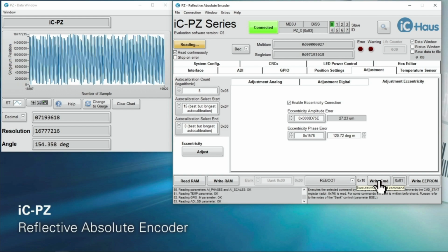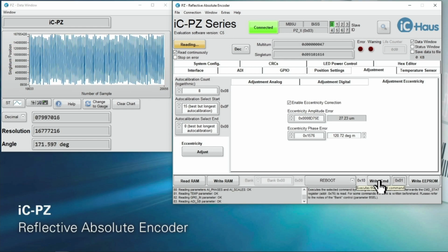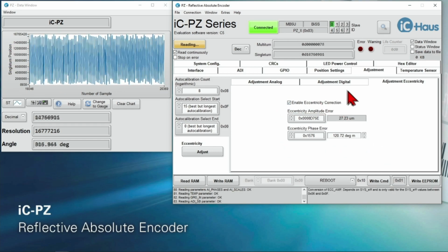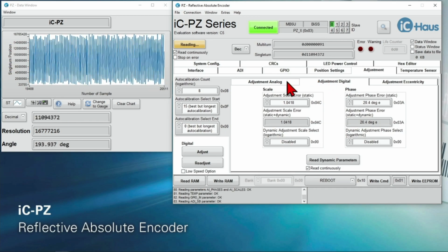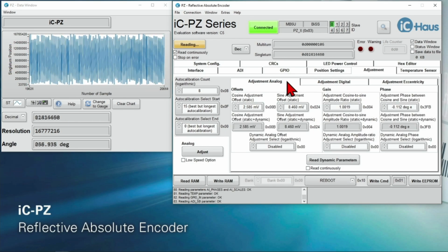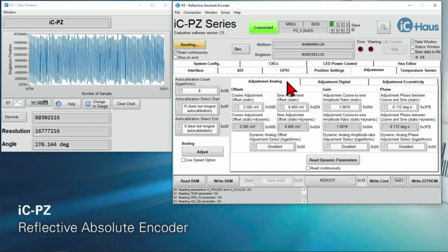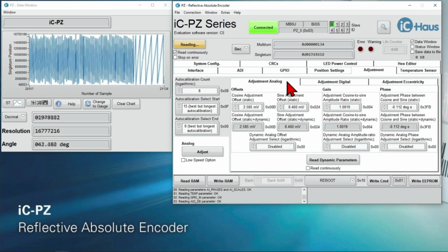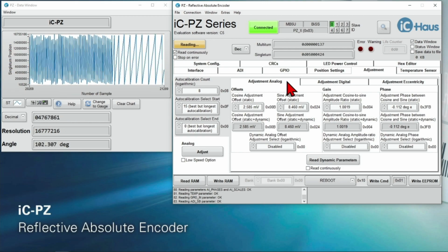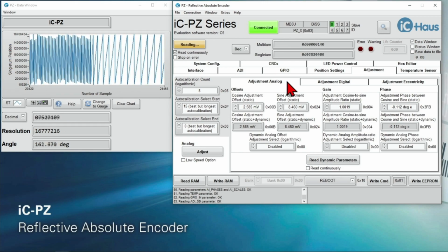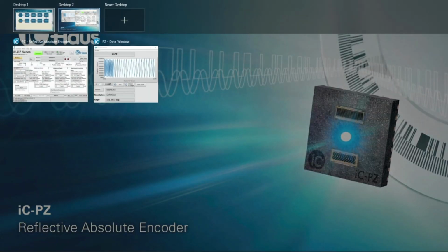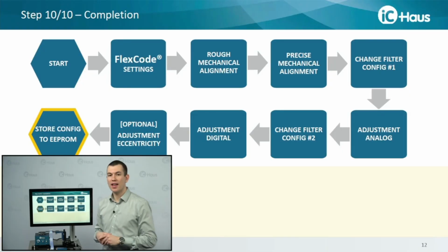And you're seeing all your auto calibration parameters and other settings you have just adapted. So the system is stored inside the EEPROM. Okay. Spinning a bit slower now so you can see the sawtooth of the position again. So that's it for setting up the system in the lab.